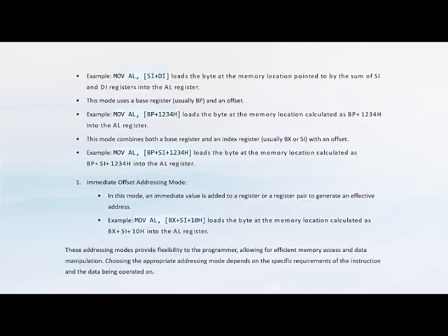One more addressing mode, based index mode. In this, the effective address is the sum of a base register and an index register. Base registers are BX and BP, index registers are SI and DI.